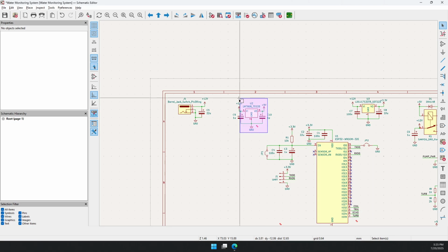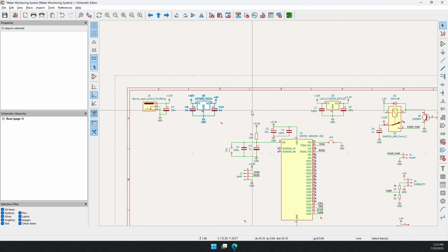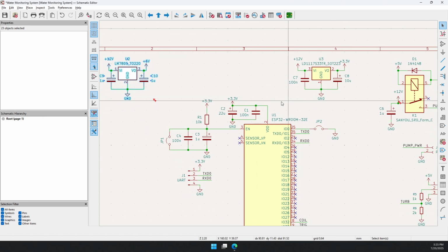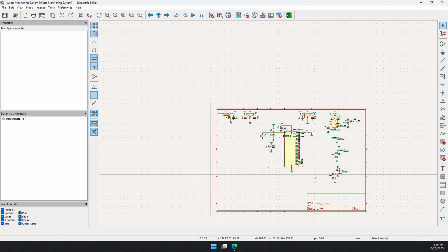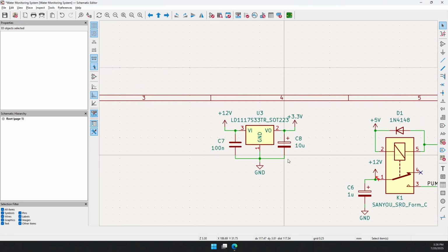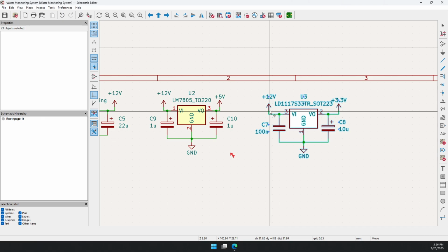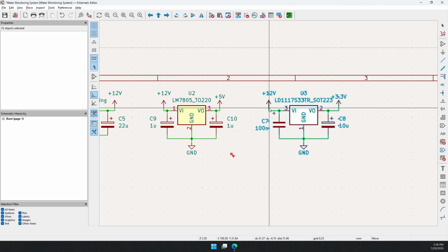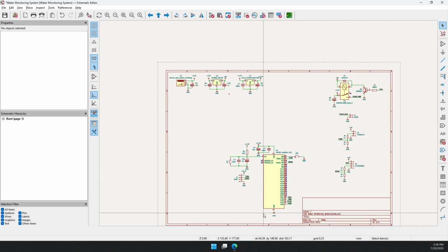So you guys get what is going on. We started from the bottom upwards. We focused on our ESP32. We assumed that there was 3 volts somewhere there, and now we are doing the actual power supply. So yeah, in PCB design where you see those complex stuff, just know that it's doable. You just break it down into smaller parts and then you just work on them.